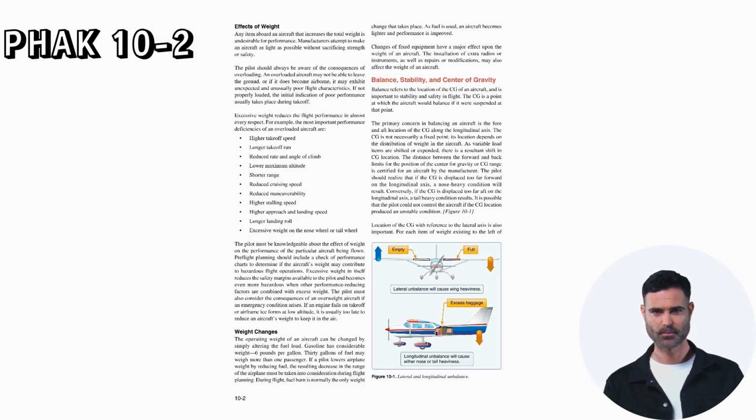Effects of weight. Any item aboard an aircraft that increases the total weight is undesirable for performance. Manufacturers attempt to make an aircraft as light as possible without sacrificing strength or safety. The pilot should always be aware of the consequences of overloading. An overloaded aircraft may not be able to leave the ground, or if it does become airborne, it may exhibit unexpected and unusually poor flight characteristics. If not properly loaded, the initial indication of poor performance usually takes place during takeoff.